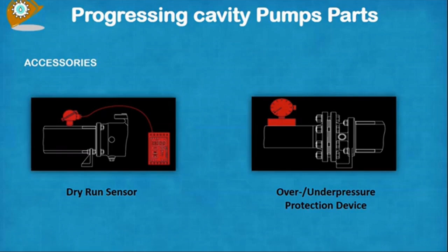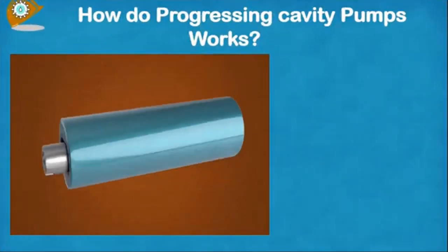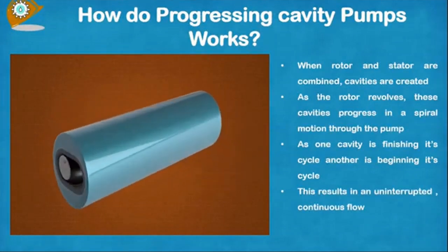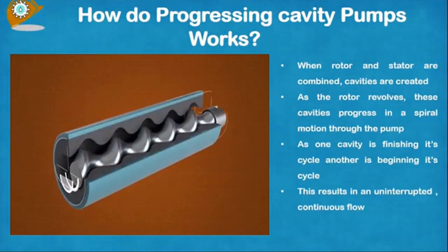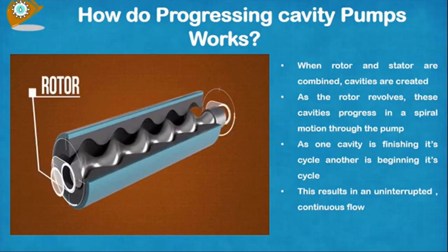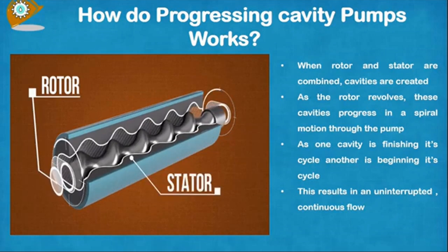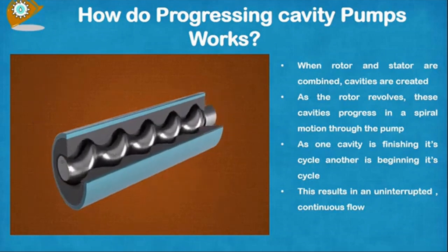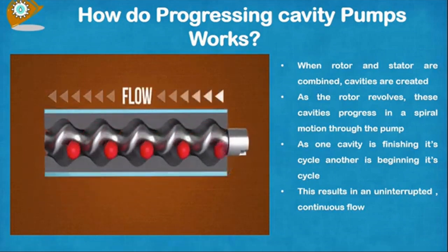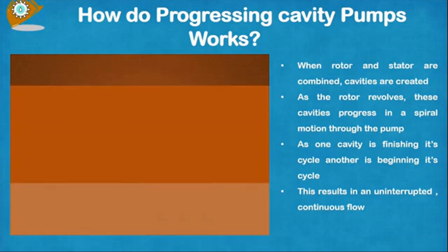A progressive cavity pump is a fluid-producing device, much like other positive displacement pumps are. Let's look at how it functions. The fluid is drawn by the pump through the suction intake and moved into an extended casing. Helical rotor and stator are contained inside the housing. Small cavities form as a result of the rotor's contact and the stator surface as it rotates. The fluid then progresses through these rows of cavities before being discharged through an outlet. Regardless of the inlet pressure, the pump maintains a consistent speed when moving the displaced fluid.